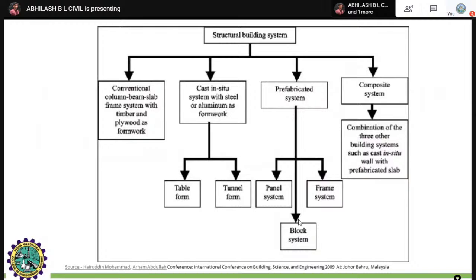Later on, you will procure the steel, that is reinforcement, the main reinforcement and distribution reinforcement, that comes to the design part of your structural analysis, right? That you will add to the particular foundation. Later on, in order to make the container-like structure for the concreting part, you will apply formwork, right? After the formwork, you will take up the concreting part. Later on, you will come to the ground level part.